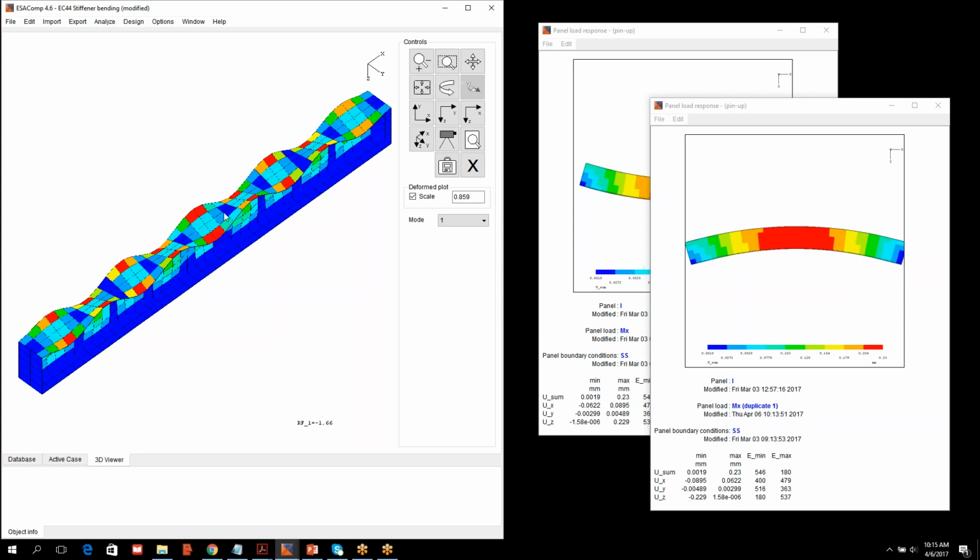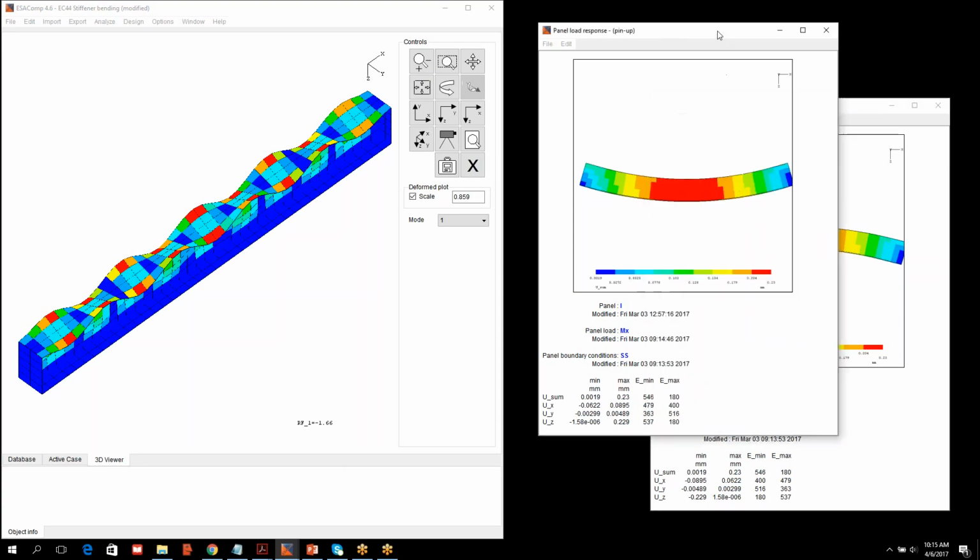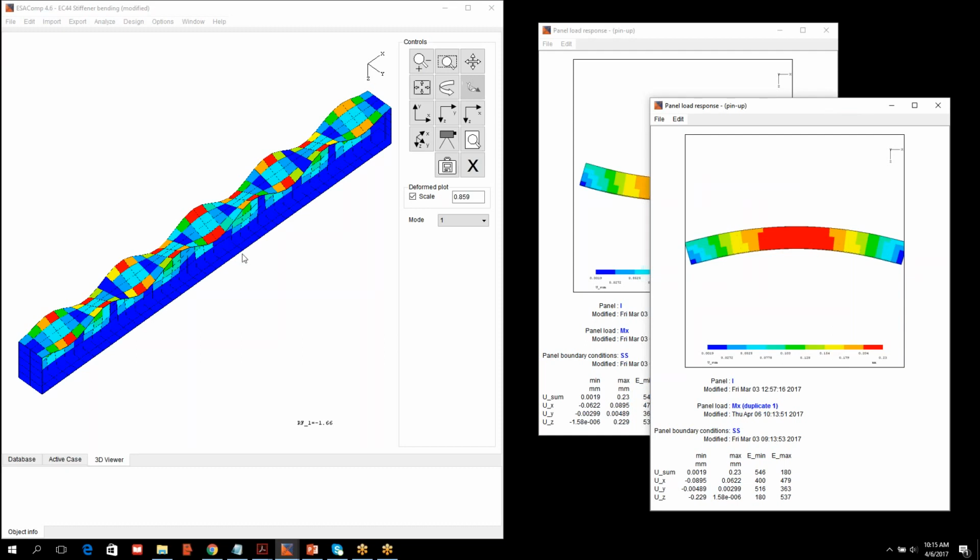The reason that the upper flanges buckle is that when you perform the buckling analysis, both of these load cases are considered. So the load vector the user applies and also a load vector multiplied by -1. And in this model, the lower flange also contains the panel, and it's stiffer and thicker. The upper flange is thinner, and the sign -1 indicates that the buckling mode shape is related to the so-called reversed load vector.